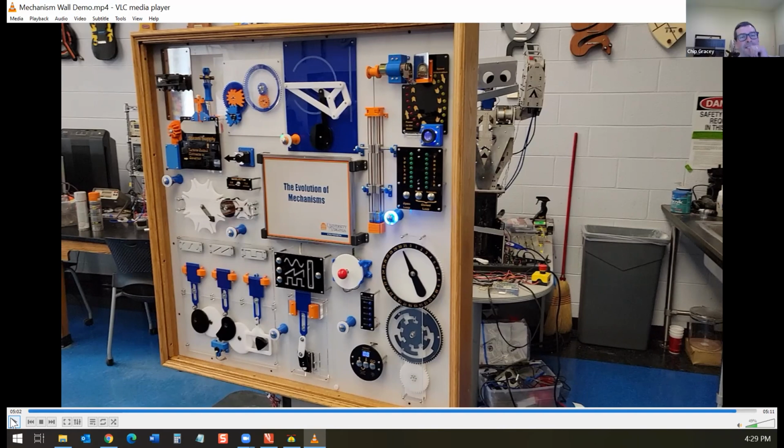So does the science really help predict pretty well, or is it always off a bit? It does. I've found that because the 3D printing process creates sort of an anisotropic material, because it's layering things, the material is definitely weakest along the little lines that it's putting down as it prints up the part a little bit at a time. So it's not a perfect model. They usually just use an isotropic model, the same material properties in all directions, as they're doing the finite element analysis. But it's close enough to kind of show the power of why engineers use math,